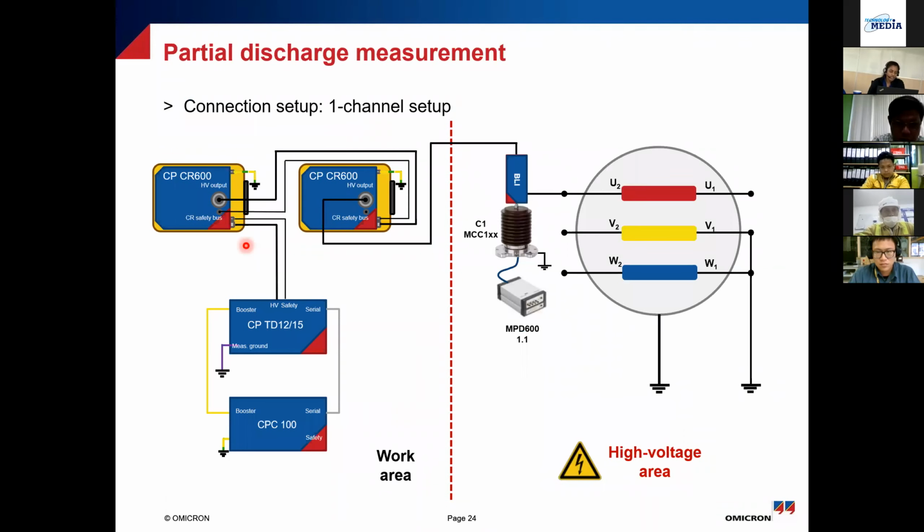Again, coming back to this, what I wanted to show you was that when you're doing partial discharge for offline measurement, let's say you have a shutdown and you want to do capacitance and dissipation factor measurement, you're using this kind of device. This is from Omicron, but you are using this kind of device as a source. You need a compensating reactor because the capacitance is high. If your capacitance is not too high, you might not need it. That's a story for another day.